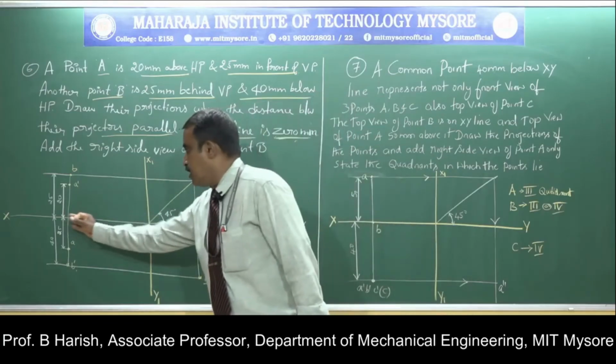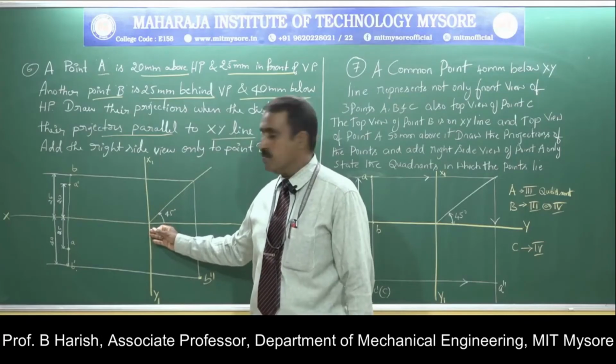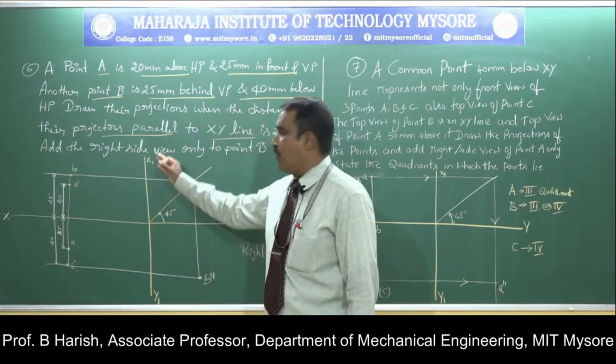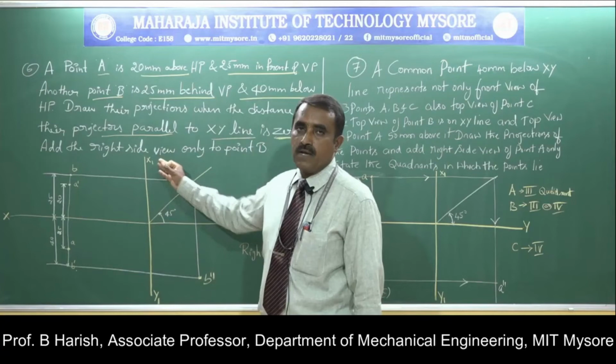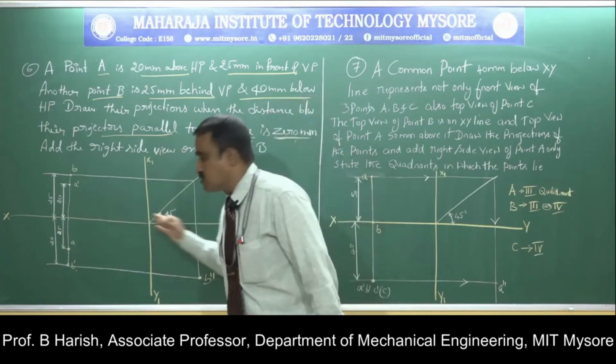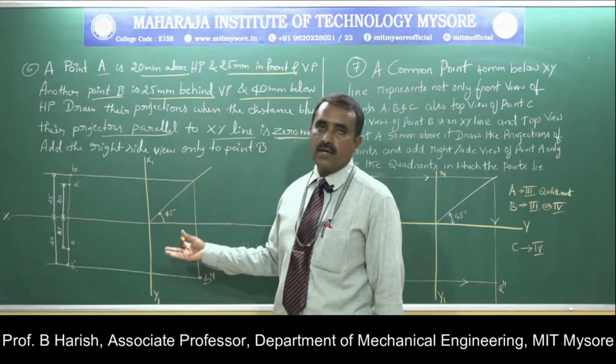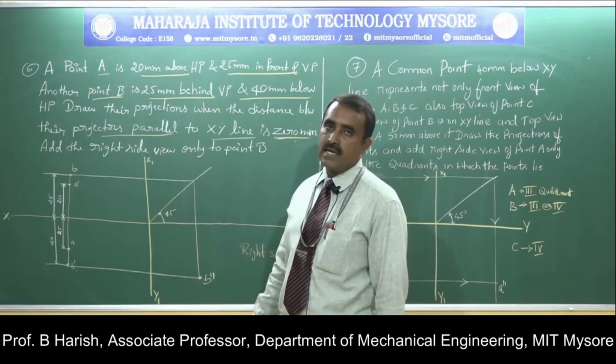So from this projector, measure any distance that you assume. There you fix your profile plane. That is your x1, y1 line. This distance is not given, so when it is not given, you can assume any convenient distance.